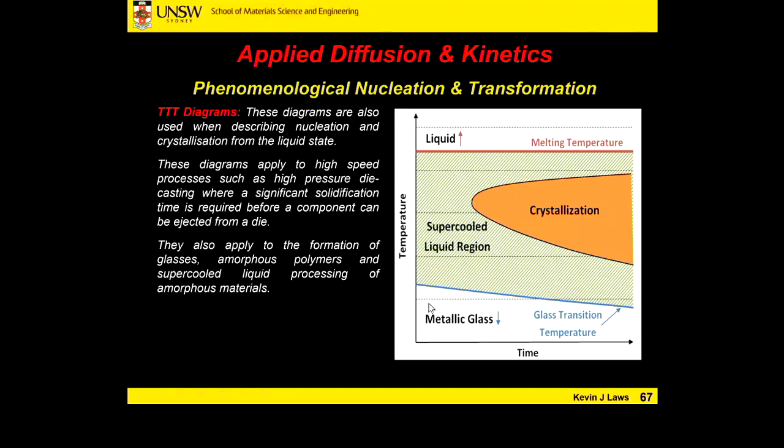With this glass transition line here, you'll also notice that it's curved, to an extent. Over a long, long period of time, this glass transition temperature would start to approach maybe room temperature, or whatever your holding temperature is. Eventually, over a long period of time, or even a short period depending on the system, this line will touch the temperature that you're holding at, and the material will crystallize, because the supercooled liquid state is metastable. It's not stable. It's not the equilibrium state.